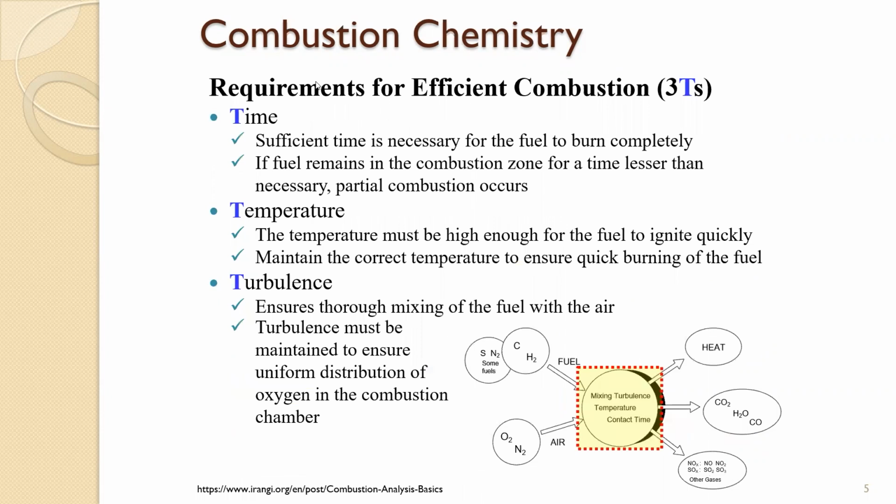So what are the requirements for an efficient combustion? Remember the three T's: time, temperature, and turbulence. So it needs a sufficient time and then needs a certain temperature high enough for it to support combustion, and it has to have air, the thorough mixing.